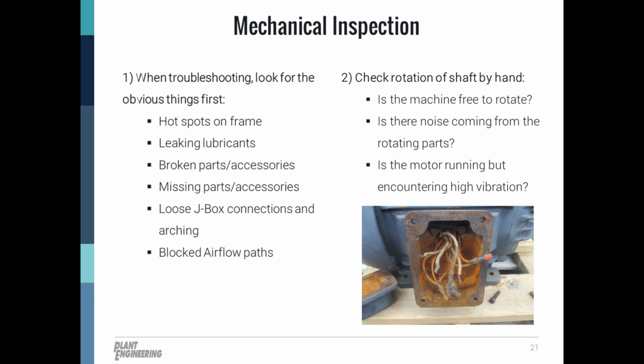So in some cases, you're suspecting a mechanical issue before it becomes a failure. You notice high vibration coming from the motor, but not very clear on where the source is coming from. In this case, that's when you can perform vibration analysis.